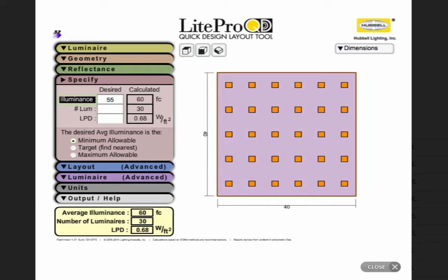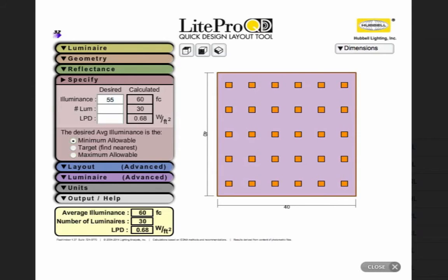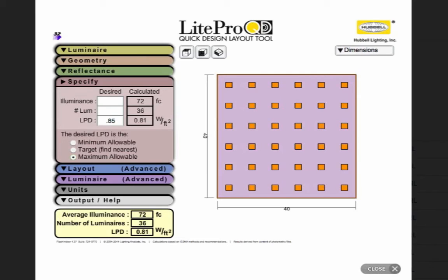By default, the app considers the illuminance you put in to be the minimum allowable illuminance for that space. But you can change that to be a target illuminance, and it will find the closest illuminance on either side of that value. Or to be maximum allowable illuminance, and it will find a layout with the nearest value below your target. Instead of a desired illuminance, you can also target a specific number of luminaires or a specific lighting power density. If I choose a maximum allowable LPD of 0.85 watts per square foot, I see that I can go all the way up to 72 foot-candles and still come in under that LPD.